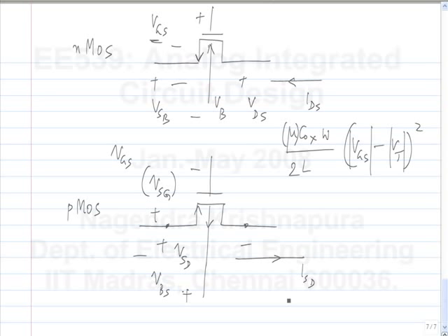We'll come to that when I discuss the models. I'll show you. The GM of the transistor is higher, meaning if you have two devices, one of which is operating in subthreshold and carrying, let's say, 1 microamp, and the other is operating in strong inversion, also carrying 1 microamp, the GM of the subthreshold transistor will be higher. But for this to happen, you know that the subthreshold transistor has to be a lot wider, right? It's carrying the same current, but it's much wider. So that's why the GM is higher.